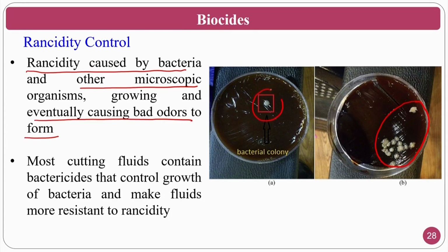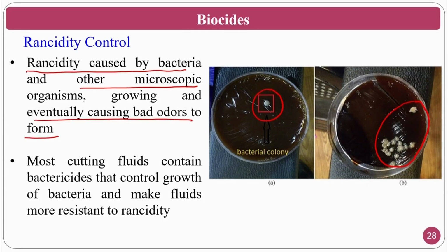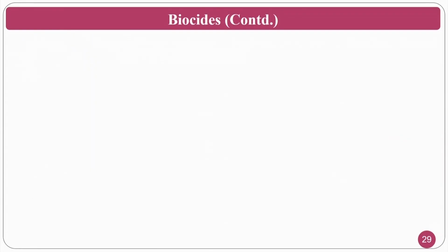If you see here, a bacterial colony has formed. If it had been mixed with biocides, what would happen? The lifespan of this particular grease or lubricating medium would have enormously increased. Most cutting fluids contain bactericides that control the growth of bacteria and make the fluid more resistant to rancidity. Rancidity means it is causing a bad odor. Normally, if you smell it, you will get a very bad smell.